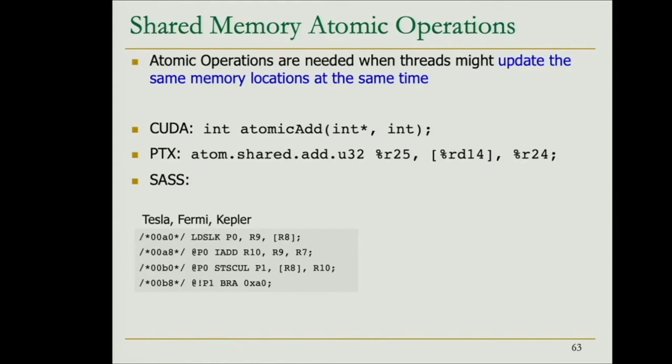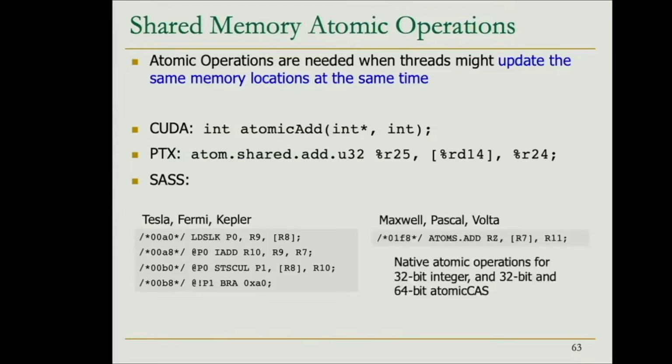Yeah, in this case, there has been a change here. And that's actually something nice that shows how much improvements in the hardware can impact the overall performance of programs. In the initial architectures, Tesla, Fermi, and Kepler, this atomic shared add was compiled into this small loop.